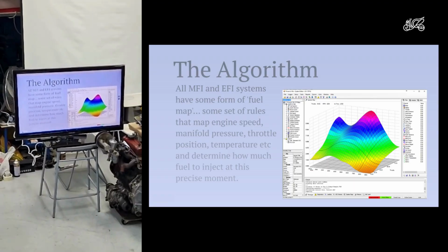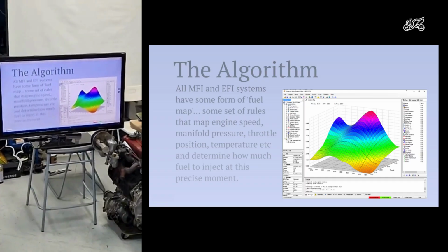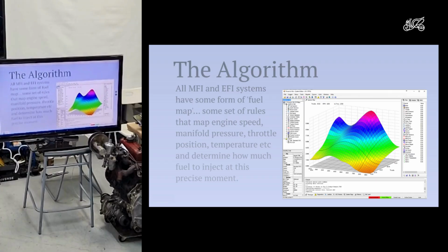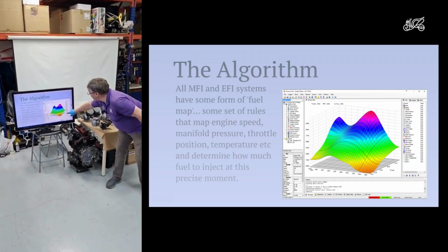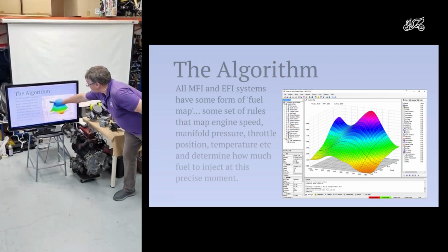And then, as I mentioned with this cone, this is a fuel map. This is a map, engine speed versus throttle position, telling me how much fuel I need. And any modern injection system has also got a map, but it's stored electronically. It's just an example I picked off the internet. So this is throttle position, engine speed, and manifold pressure.